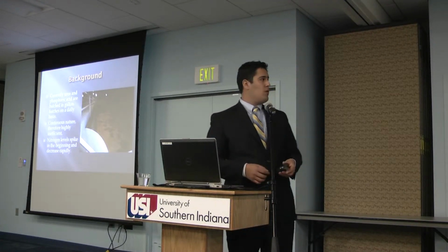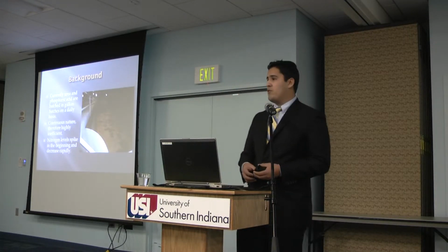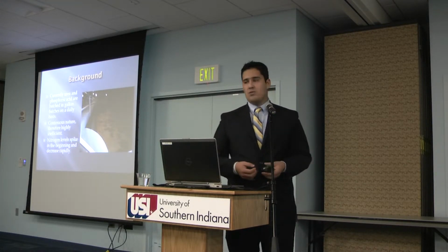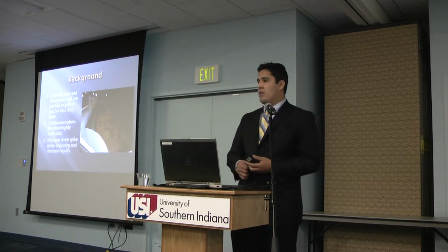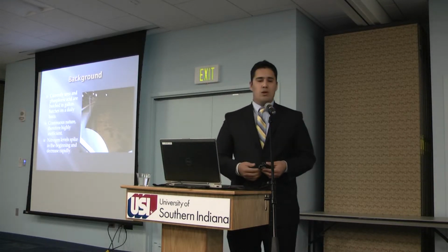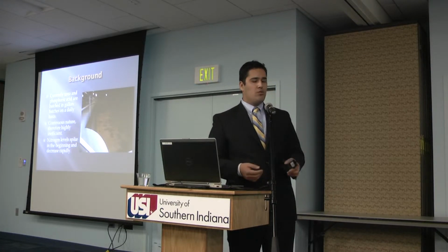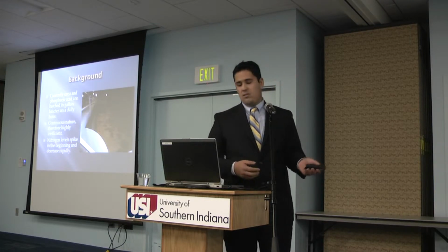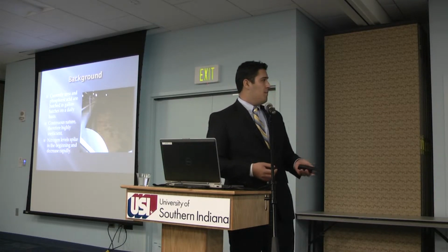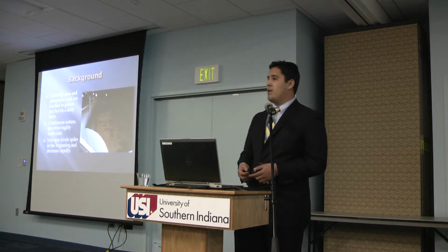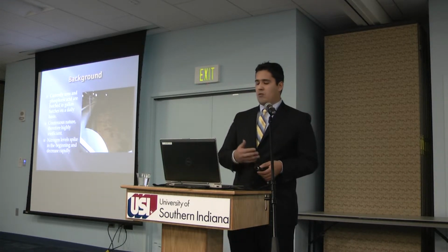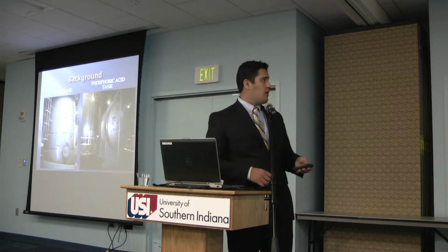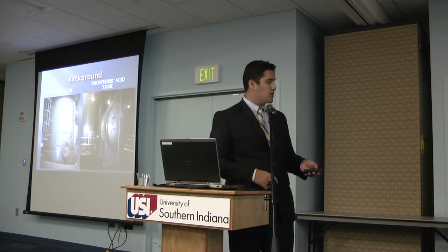As a background, currently Abengoa batches urea and phosphoric acid in gallon batches. Since this is a continuous process, it is highly inefficient, therefore a much more sophisticated way was approached in order to have a much more regulated chemical addition. Since this is highly inefficient batching, the nutrient levels spike at the beginning of the day, and then through the day they decrease rapidly. That's a picture of the urea tank and phosphoric acid tank that are in Abengoa.